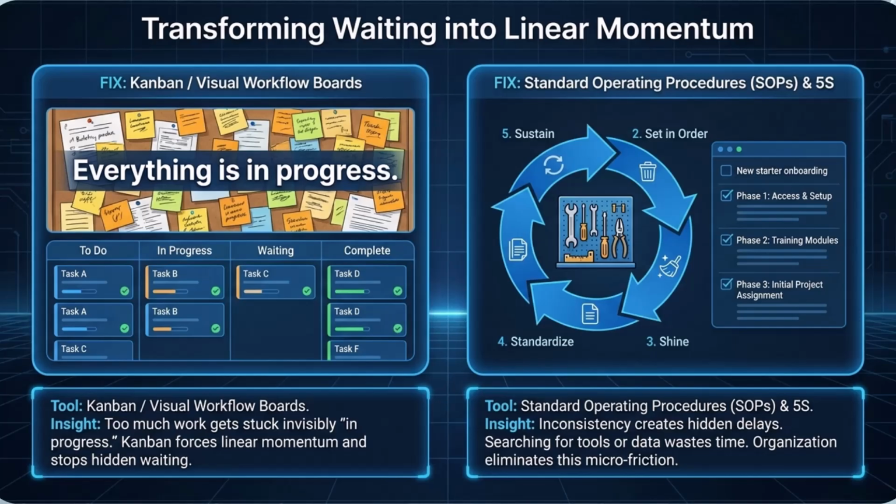The second thing is having an overall strategy of 5S. Now 5S is basically cleaning up your area, making sure it gets a lot easier to find things in that area and understand what things are actually being flowed through a particular process. And what you do is you go in there and you set things in order, you make sure things look good, you standardize the way that things look, and then you sustain the overall process with audits.